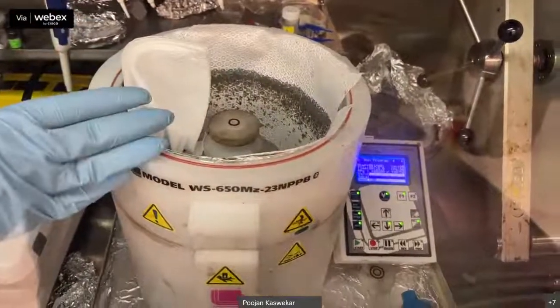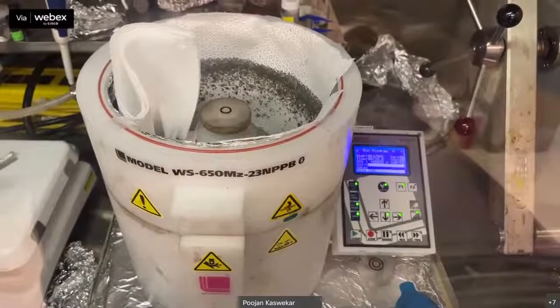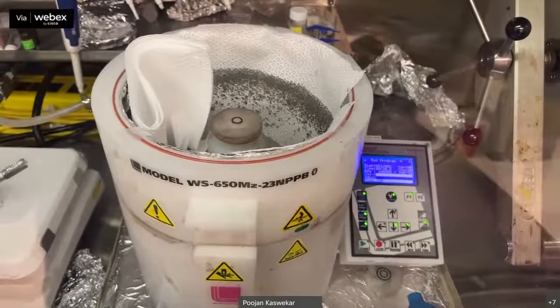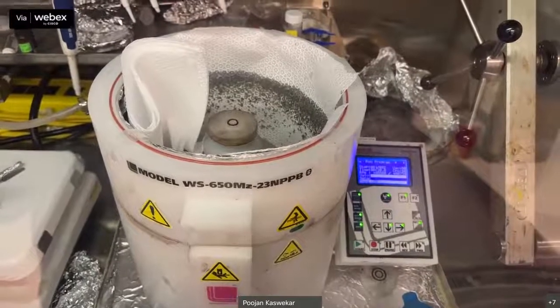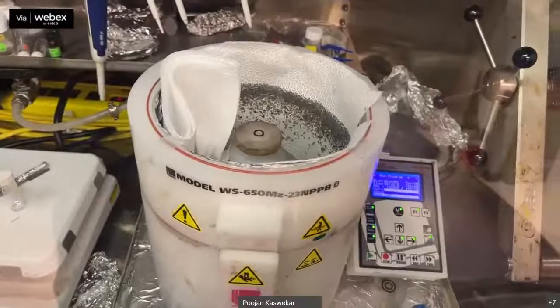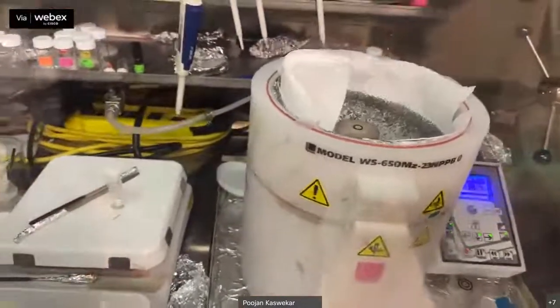By controlling the speed of the spin coater, the speed of spinning and the centrifugal force, we are going to control the thickness of the perovskite. So thickness we can measure with cross-sectional SEM of perovskites as well as with AFM also. Normally we deposit like 300 nanometer or 300 micrometer thickness.